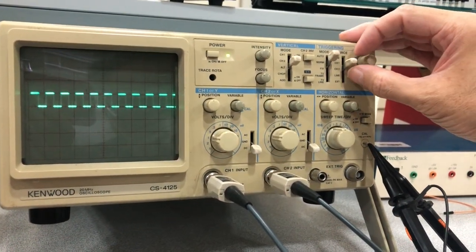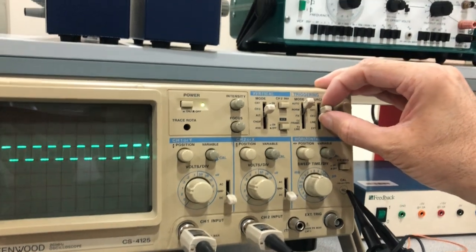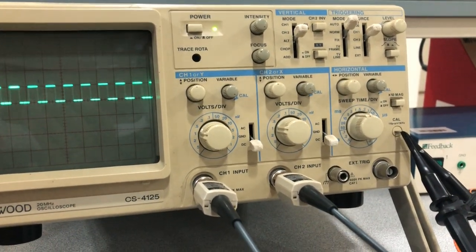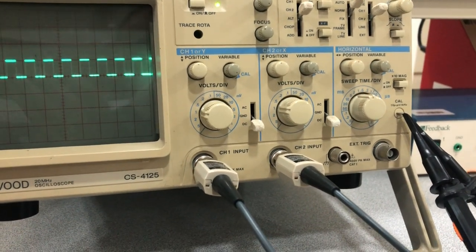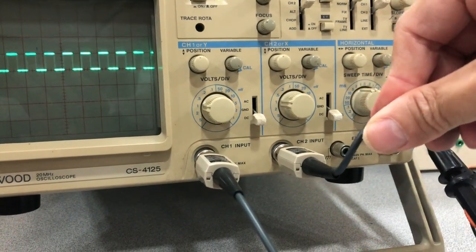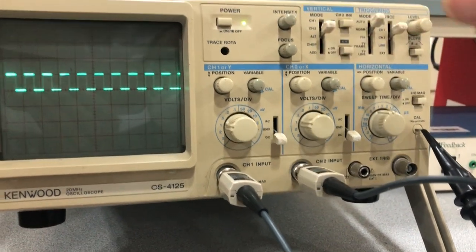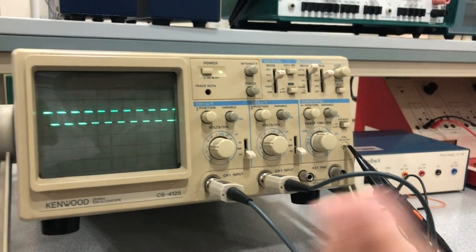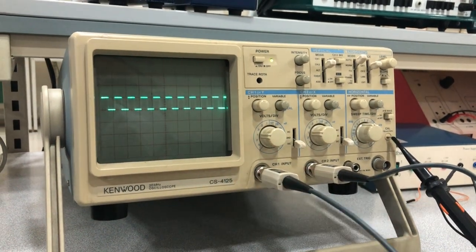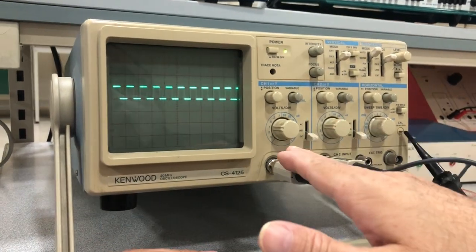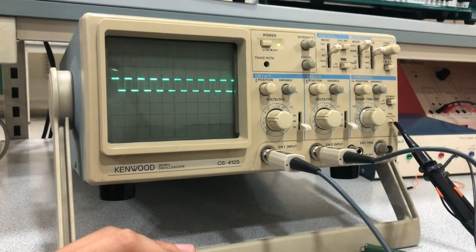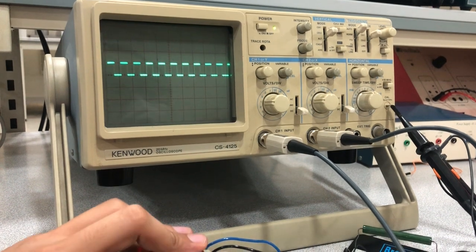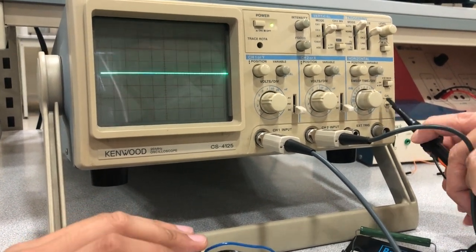So for triggering, most of the time I trigger off channel 1 and I usually plot the input to the circuitry that I'm analyzing with the scope. I plot the input on channel 1 and the output on channel 2 so that I don't lose track of which is which. We always start with the schematics left to right, and we also feed the signals to the scope so we don't get lost. Channel 1 is the input signal, and channel 2 is the output signal we want to examine, for example on the load resistor. Now we have an idea about the scope, so let's start using it on the circuit.